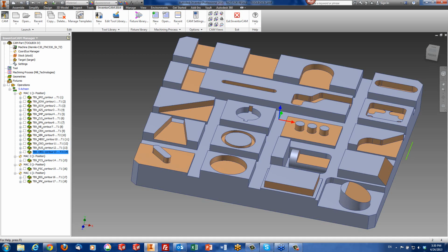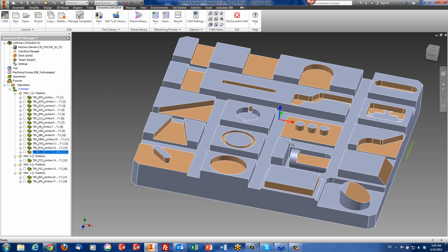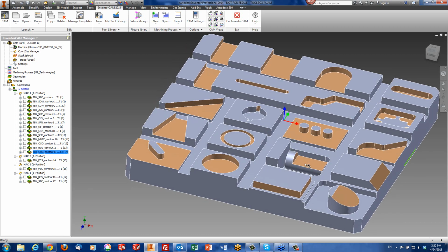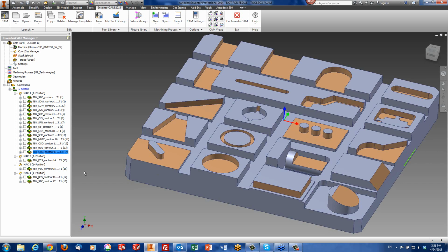There's one over here, this area over here. The idea behind this is that I want to mill off the top of this, but every single time I go down, I want to increase the length of my tool path as I'm going down. Notice in top, I want to start off shallow, and as we go down further and further, I want to have wider steps, because that's according to the material that I have over there. Opening up the operation.